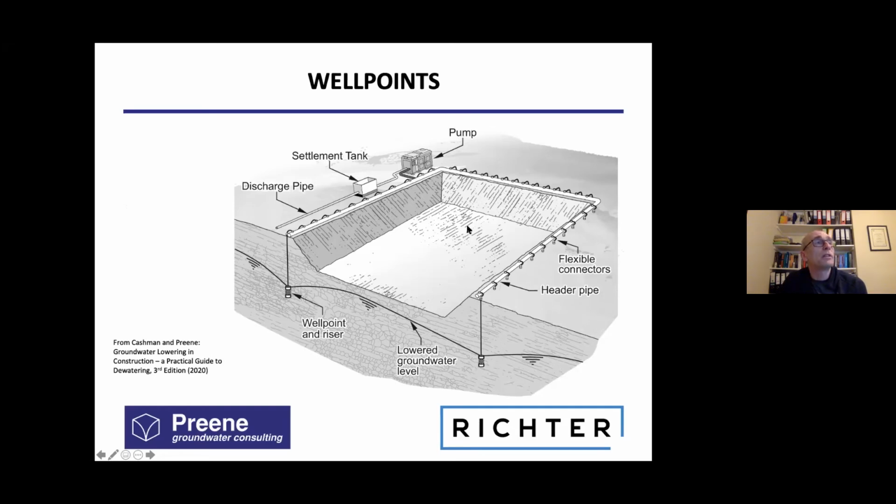The way that the wellpoint system works is we have a pump here that creates a partial vacuum, a pressure below atmospheric pressure, and that partial vacuum is transmitted around the excavation in this header pipe that's normally about 150 millimeters diameter. Every 2 meters or so, we have a well point that's connected to the header pipe by a flexible connection with a valve. So basically the partial vacuum starts in the pump, it comes round along the header pipe down into the well point. The well point has a perforated filter on it, and so the partial vacuum here draws the groundwater in, lifts the groundwater up, and the water from all the well points is collected together and discharged away. Effectively, the header pipe acts as a manifold, which means that just one pump can pump on anywhere from 50 to 100 well points at any one time. So it can be a very effective and efficient way of pumping.